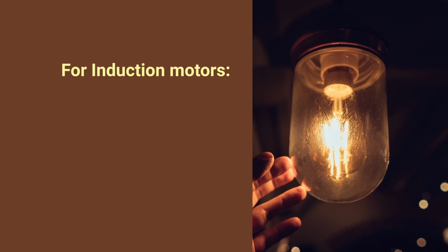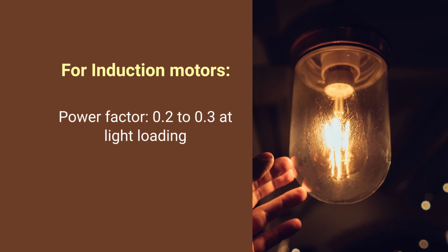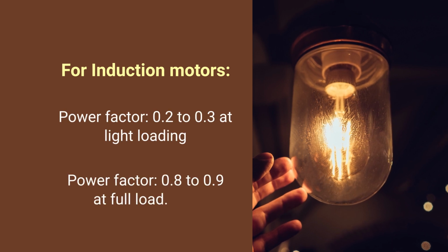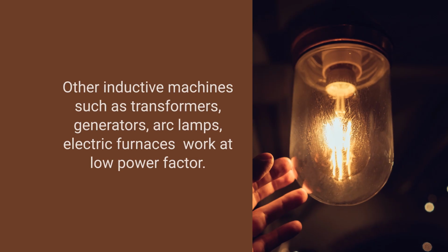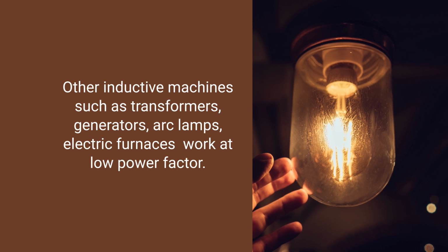For an induction motor, the power factor is usually extremely low, from 0.2 to 0.3 at light loading condition, and it is 0.8 to 0.9 at full load. The current drawn by the inductive load is lagging and results in low power factor. Other inductive machines such as transformer, generator, arc lamp, electric furnace, etc. work at low power factor also.